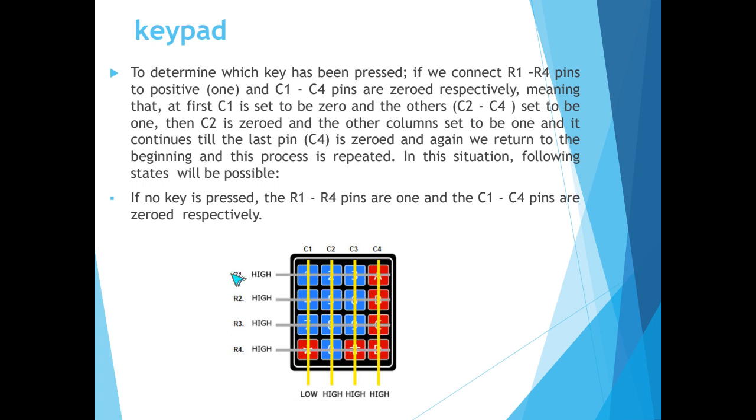Listen to me. If I connect all of these rows of my keypad to positive 1, meaning that I configure them as input and activate their pull-up resistors, okay?